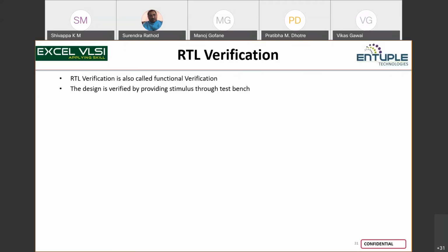Verification takes a lot of time throughout the ASIC cycle. It is not only RTL verification; it could be gate-level verification, physical verification, DFT verification, static timing analysis, and formal verification. Even after the chip comes out it is still verification: the DFT patterns, the ATE (automatic test equipment) test cases you run, and ATPG. After that, you do silicon validation to check whether the silicon is functionally okay.